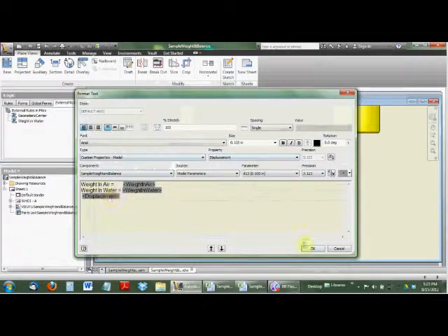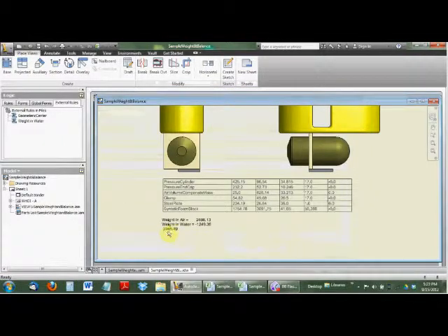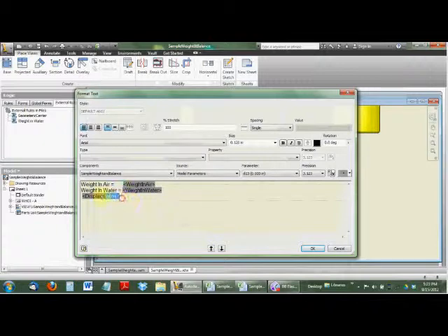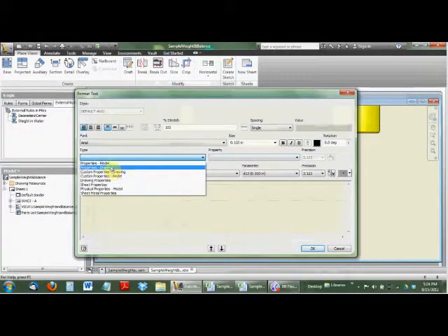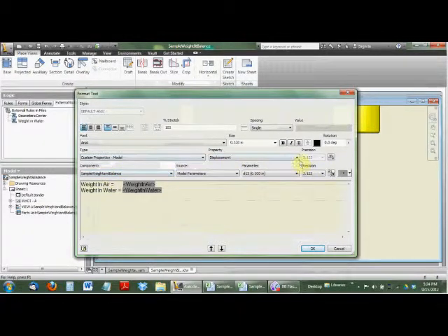And down it goes, we say okay, and there you go, that's the displacement right there, in pounds. We don't need the displacement again. That's how you go about business there. It's very straightforward. Your variables will, once you choose custom iProperties over here, custom properties models, your variables will come up in a list and you can choose from them.